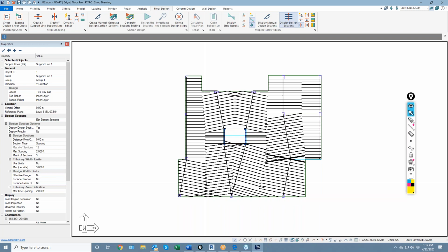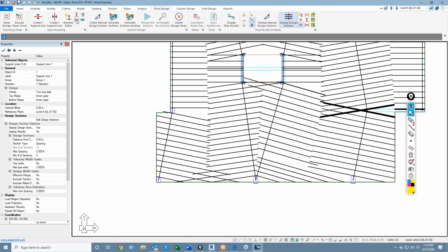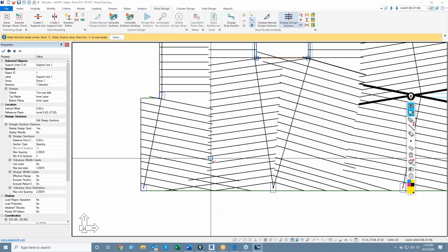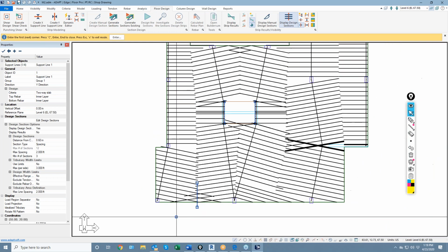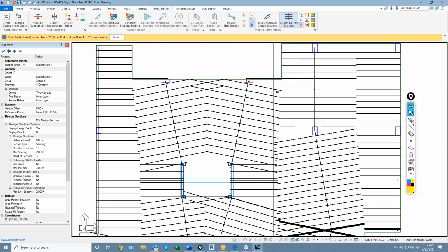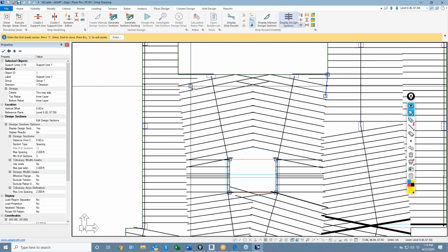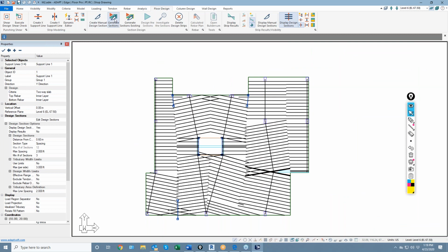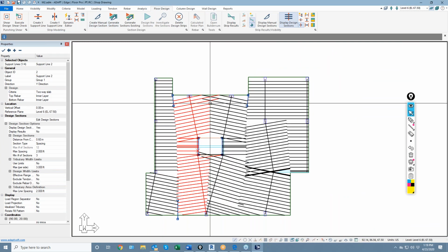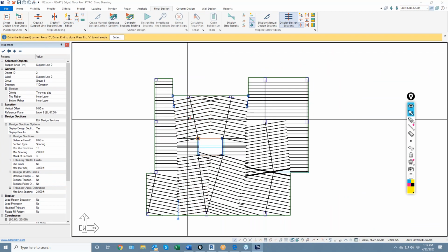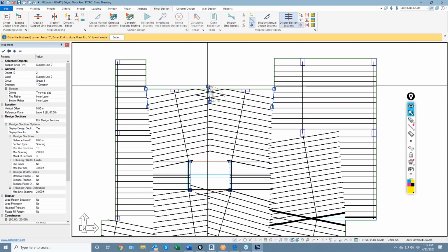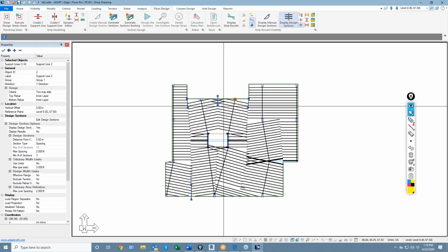If I want to clean this overlap up right here, I could just run another splitter just there and run it out of the slab. It's fairly forgiving in terms of how you can use these splitters. So I'll add another one there, and maybe another one there. And if I regenerate, there's a little bit of overlapping between these two, so I'll do one more along there.